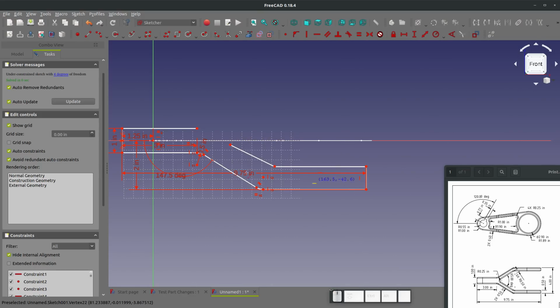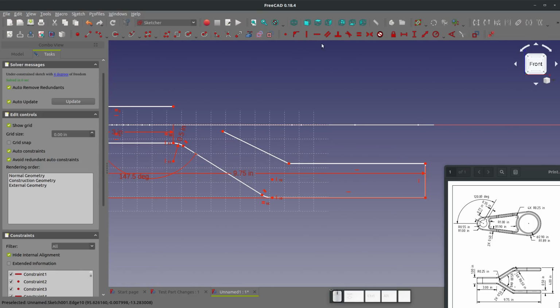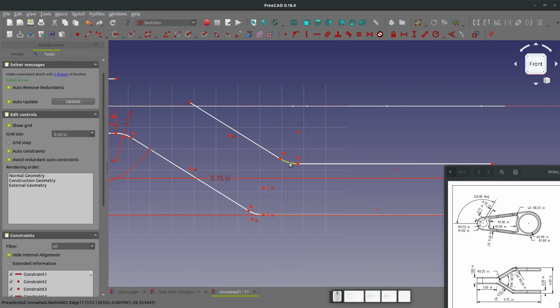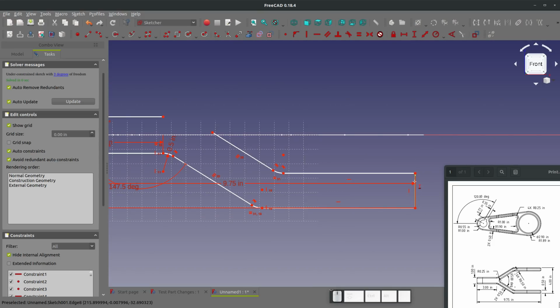If you're tired of adding fillets, let's add in a parallel relation there. We'll grab a fillet, and you can also add an arc that way. It's nice because it adds the tangent relations as well. We'll go with equal. Shift V for vertical. We'll get 0.5 inches there per the drawing. And then we need to add a thickness. It looks like 1/2 inch thickness there.